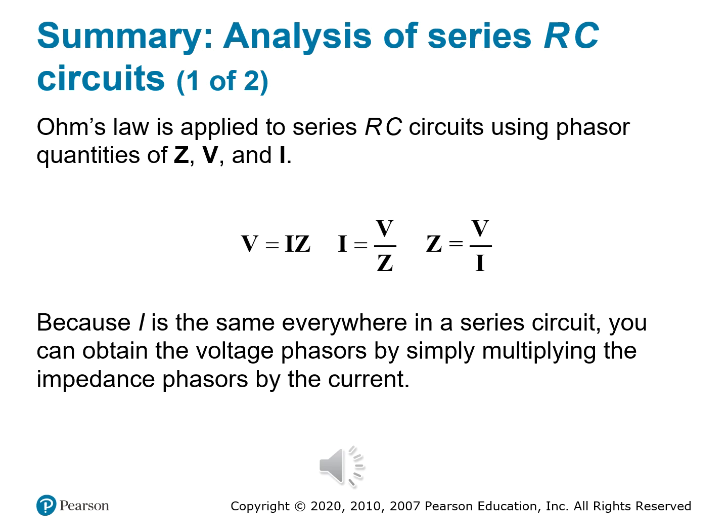Across the resistor, V sub R is equal to I times R, which is in phase with the current. Across the capacitor, V sub C is equal to I times X sub C, but it lags the current by 90 degrees. And these voltages are phasors too. So together, they vector sum to the source voltage.